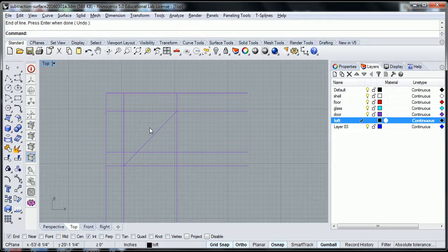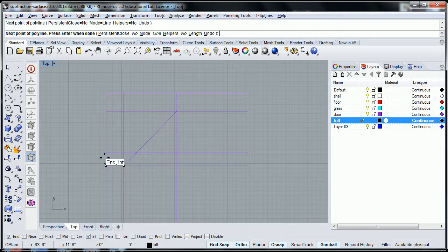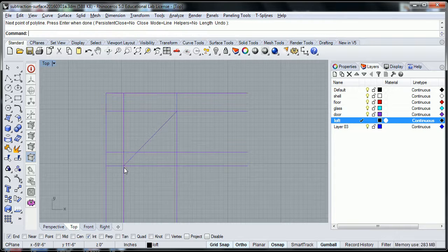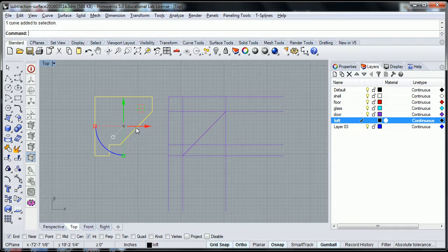Now all we have to do is trace using the P-line tool, the polyline tool. So left mouse button and just select up to here, not all the way, up to here, and then select the little divot and then to the end point. When we do that, you should be able to move this off to the side, and you have just drawn yourself one loft.